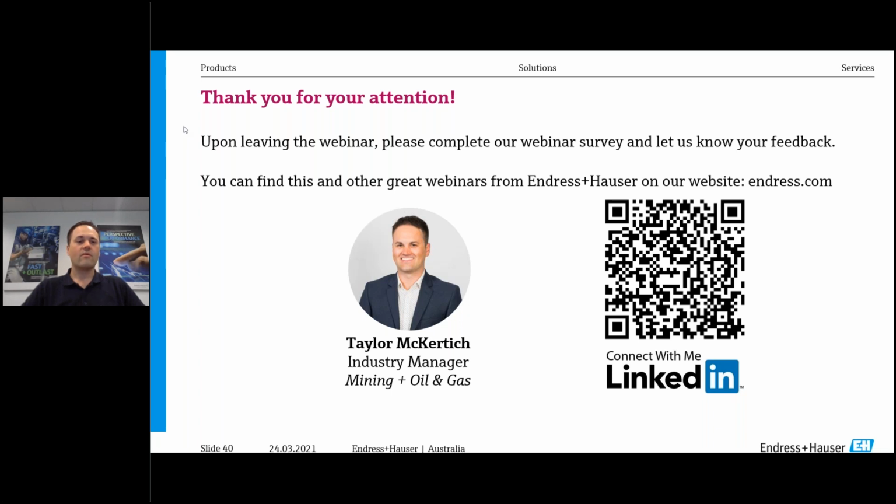Okay, I've got one more question. How long does the radiometric measuring principle device last in the process? The source life itself depends on your local requirements as well, about 15 years. Depending on the local requirements, you'll have to make sure that you have licensing and an RSO, and there are a lot of fees and regulations around that too. So using a non-nuclear density source for monitoring, or one of the ones that I discussed here, is a good way to ensure that you don't have to go along the route of licensing or having an RSO or something like that.